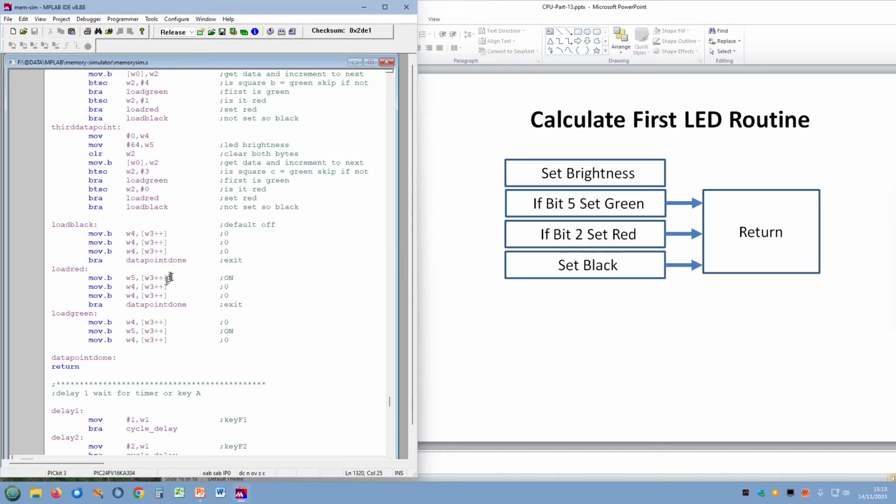So we've got red is first, green is second, and blue would be the bottom one. If you wanted blue, you put the value in the third byte. So that's for red. For green, as I say, we put it in the second one there. So we've got 0 of red, 64 of green, and 0 of blue. If you wanted to change the brilliance, so you change the number in W5, you notice the green comes a bit brighter than the red. Or you could change the value that gets written, so instead of putting that value in, you could put an actual number that gets loaded in.